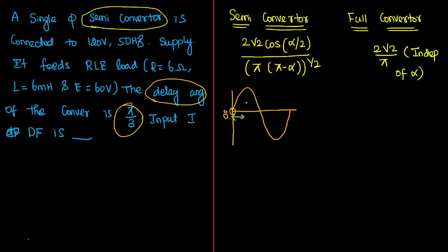We are allowing this waveform to travel through the SCR. The delay provided by us is simply called the firing angle. We are firing the SCR. Okay, sir. So the conclusion is that delay angle is known as firing angle only. That value is already clearly given. Now substitute the value of alpha equal to pi by 3, and you will come up with the answer. At least drop your answer now. If you replace alpha by pi by 3, what will you get?